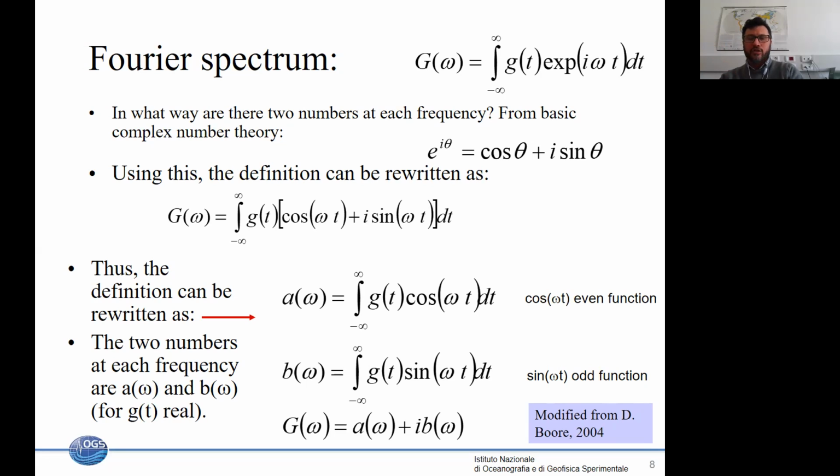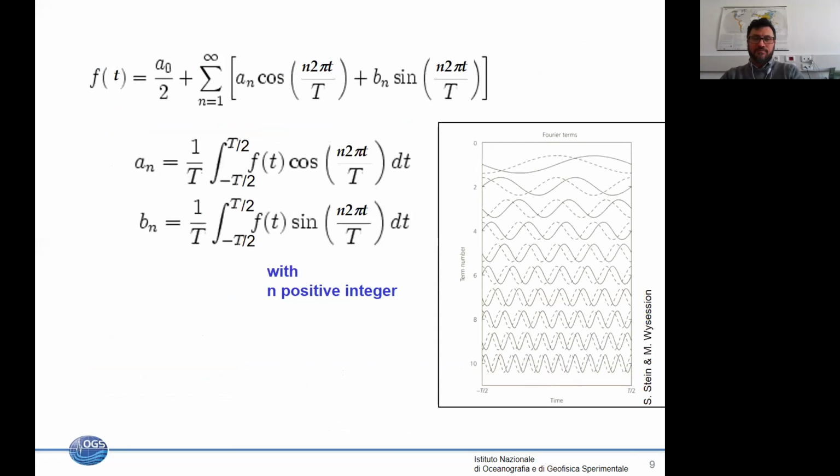So what we are recording is not the original shaking of the ground, but the response to this shaking of the instrument that is measuring it. So if we want to go back to the original shaking, if we really want to measure the acceleration, the velocity of the ground or its displacement, we have to remove later, through the deconvolution, in this case, the response of the sensor.